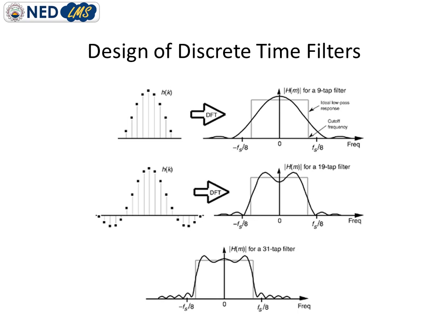So which type of response will this filter give? This can be easily calculated by taking the FFT of this impulse response, because the impulse response is in the time domain, and if I take the FFT then it will be the frequency response in the frequency domain. So here you can see as I increased the number of filter coefficients, my response becomes sharper.